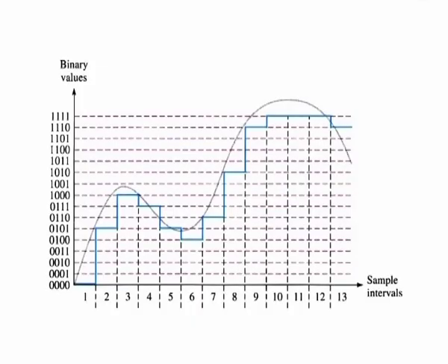As you can see, the result is much more like the original waveform than for the case of 4 quantization levels in the earlier figure. This shows that greater accuracy is achieved with more digitization bits. Most integrated circuit ADCs use from 8 to 24 bits, and the sample and hold function is sometimes contained on the ADC chip.